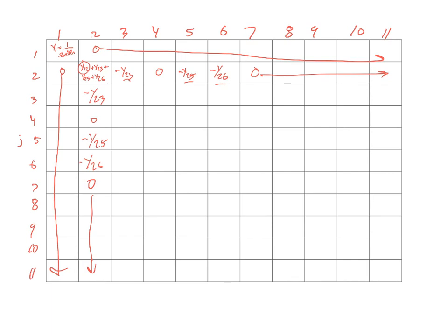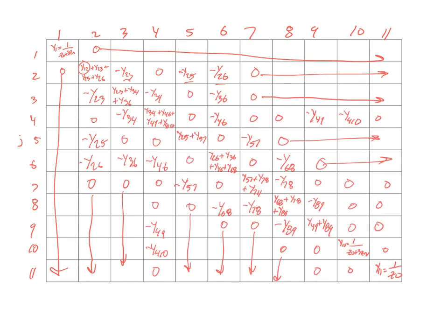So at this point, I'm going to go ahead and fill in the blanks quickly. You can take a look at your diagram and try to fill out the blocks yourself, which I highly suggest you do. It will make you way more efficient in actually building these. So next time you hear from me, this diagram should be completely filled in. All right, so here's the final filled in Y bus for the zero sequence diagram.